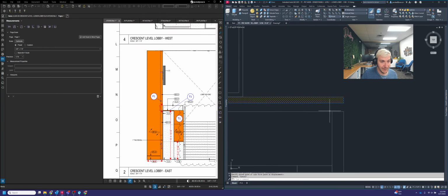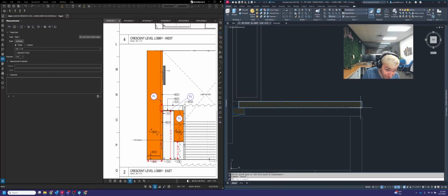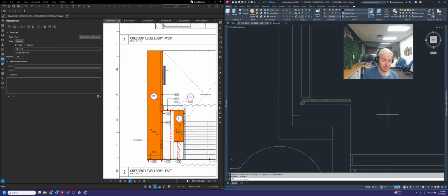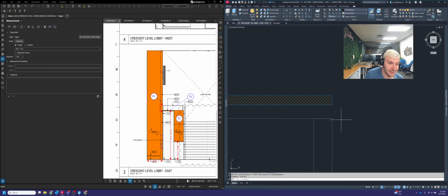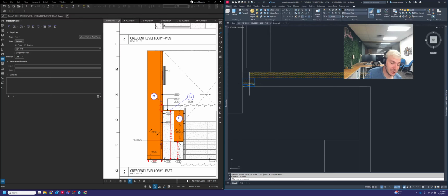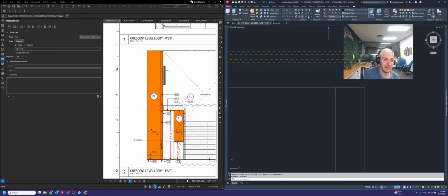All right. And then we need to add a reveal block here as well. This one's a little bit different, a little bit more tricky, because this is a 1-inch gap. And over here we're showing shim, but we can't show that shim here because you would see it in the room. So to prevent that, we're going to draw in a block at 3/4 thick still, but 1 inch tall.